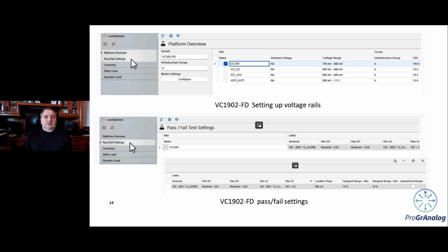So that's where you essentially develop your test vectors for testing this device. And you also set the margin. You're going to see the margin in a few more slides. You'll see the marginality, right? A lot of feedback has been, okay, that's cool, it's a pass or a fail, but where does it get close to a fail? Because that's where we want to hone in. Quite often that's going to allude to where a problem is, like a time constant problem. So the marginality is also configurable through this input stage.